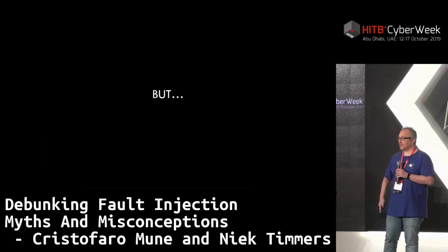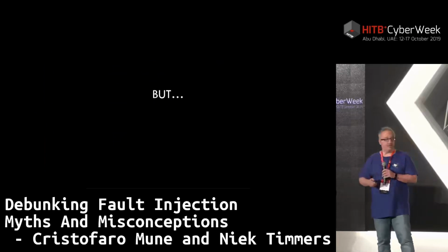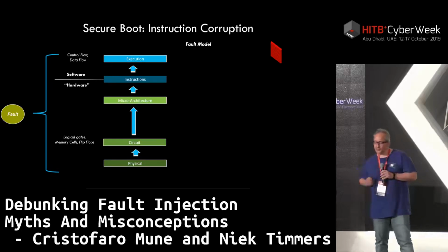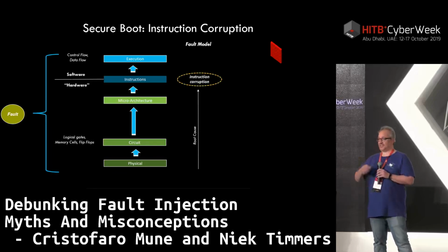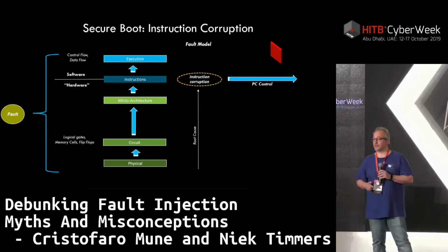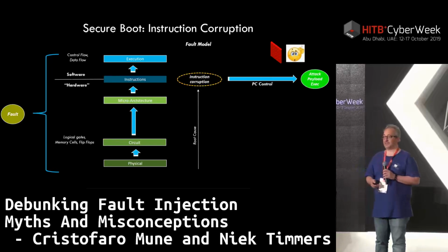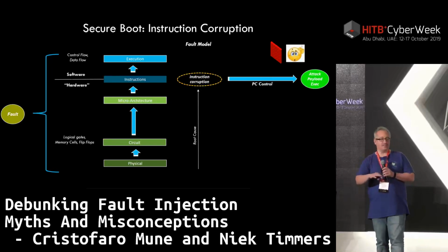But now that we know that there are different faults happening in the stack in different ways, we can use them in a different way. From 2016, we have this nice tool or fault model, which is instruction modification. So instead of focusing on skipping instructions, now we want to modify instructions. If the instruction modification assigns, as we have seen, a different value to the program counter, the program counter immediately goes to execute a flow under attacker control. So this means that the software where a countermeasure is placed is not executed, and your software countermeasure is basically useless there. You just switched to a different level, and you use that in a different way.